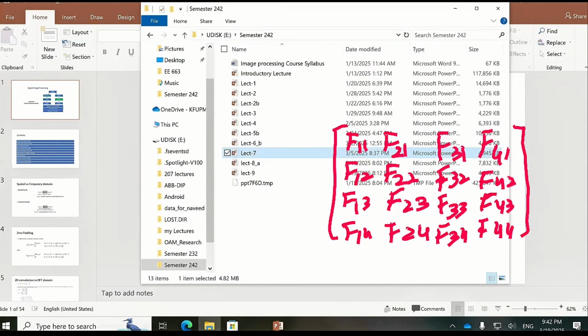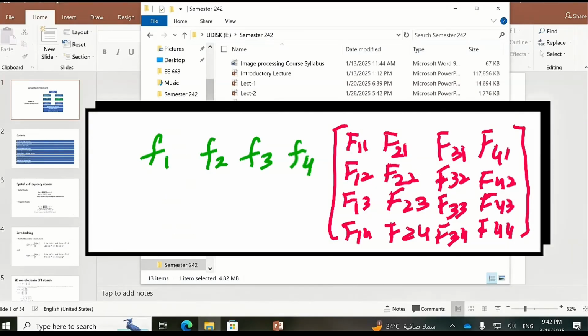So what is the size of this? It is equal to this, and the other dimension is given by the window size. Okay, so in this way, what information do I have here and what information do I have there? Here we have the frequency information, and here we have the time information. So what I'm doing is the time and frequency together. So it will be a very nice matrix showing two things: frequency and time.